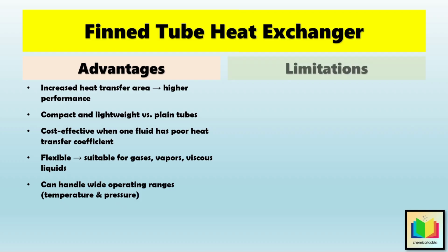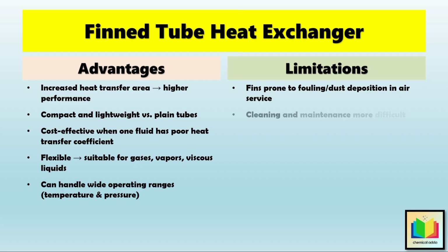Now let's see, what are the limitations of fin tube heat exchangers? So, despite their benefits, there are also some drawbacks. So the first limitation is, fins are prone to fouling and dust deposition, especially when air is the process fluid, which reduces efficiency over time. Next is, cleaning and maintenance are more difficult compared to plain tube exchangers.